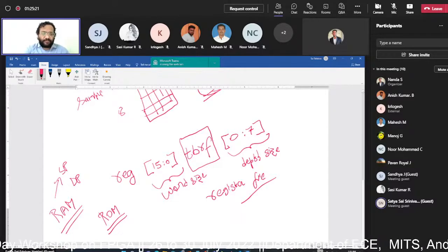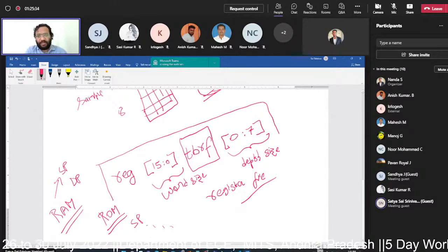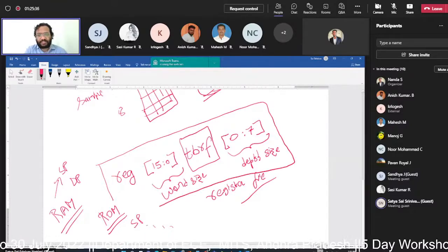In ROM also we have a single port ROM or a dual port ROM, and so on. For all these cases, whenever you are declaring a memory, we will follow this notation. This is the syntax followed in Verilog to declare memory elements or memory variables.